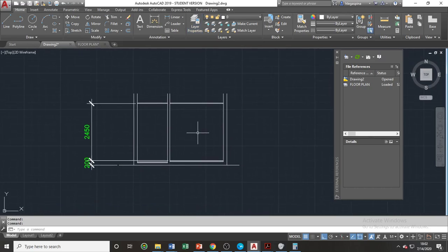If you wish to turn back on your layers without opening your layers palette, you can use the LAYON command or turn on layers command. The shortcut key for turning on layers is LAYON, or in the phonetic alphabet, Lima Alpha Yankee Oscar November.